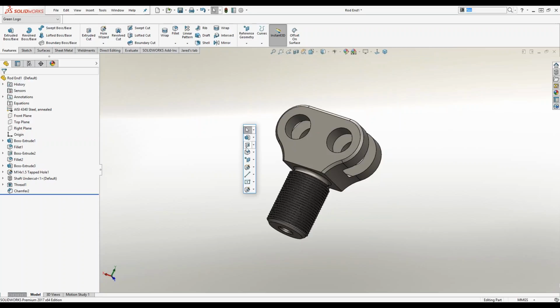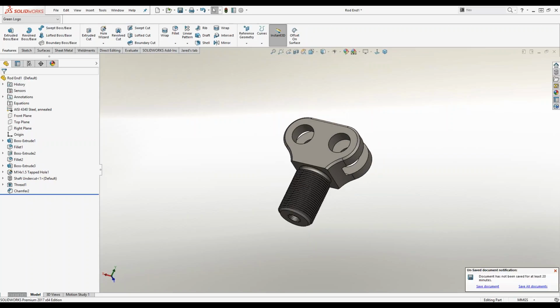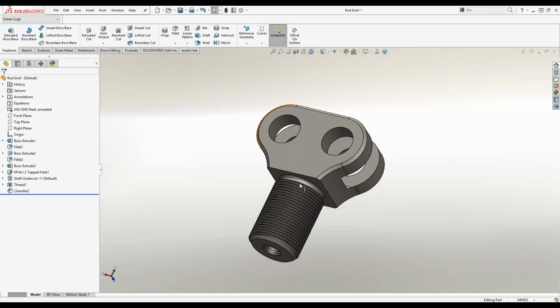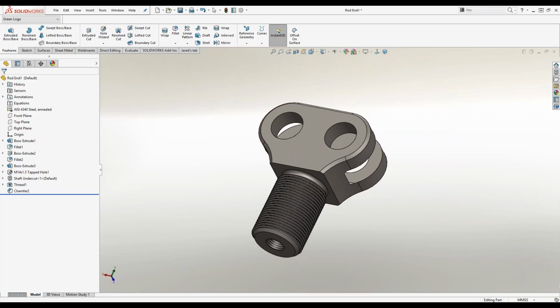The S key was the one we talked about, so here's the S key that I just set up. There's the whole wizard that I added, and a couple other ones in here that I keep, sometimes I use a lot, like the line and the rectangle. And then the other one we discussed was the mouse gestures. If I right click and hold that right mouse button, you can see the different mouse gestures available. And there's the zoom. If I click on that, I can automatically access that zoom command. And then the escape key will bring you out of that mouse gesture.